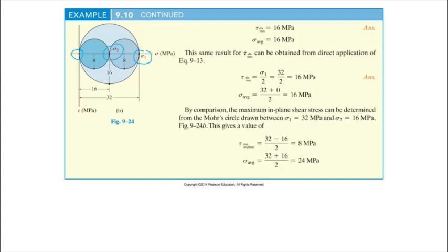Okay, the one on the right, right? And the other two, the smaller circle on the left and the largest circle in the Mohr circle diagram, are both out of plane. So our maximum in-plane shear stress is this one, which is smaller. So that is tau max. In our case, we can call it x prime, y prime, or just in plane. Okay. Sometimes you write that, or sometimes you just write in plane. So everyone knows that this maximum shear stress is in plane.